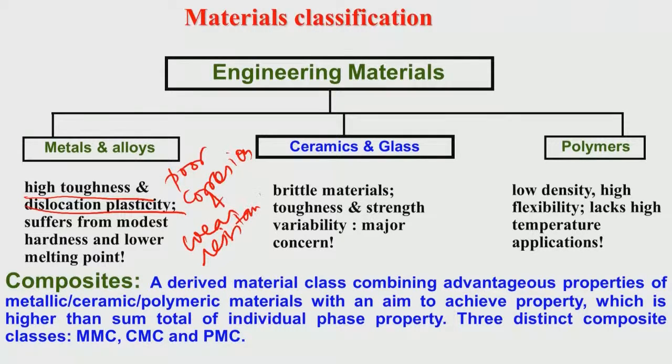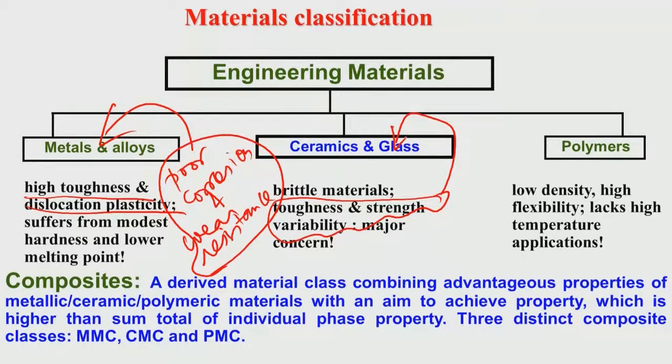materials, when implanted, will experience a physiological medium, and in the human physiological medium the pH and temperature are not uniformly the same throughout the body. So, they dynamically change. Under this dynamic change of pH and so on, these materials would experience corrosion and wear related phenomena, particularly at the articulating joints. So, this degradation in material properties is quite obvious, and that has been an issue for metals and alloys. Now, for ceramics, as I said, fracture toughness is an important limitation, because they are brittle in nature. Another one is strength reliability.